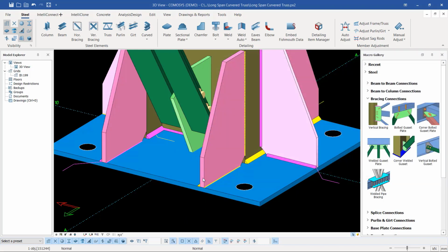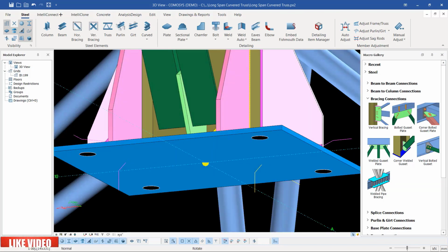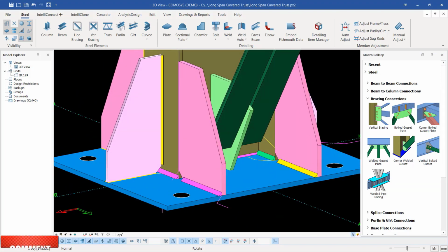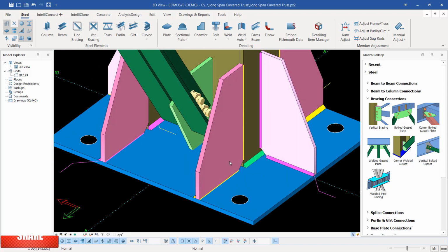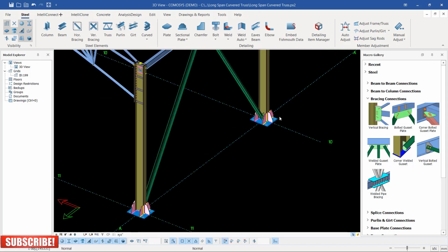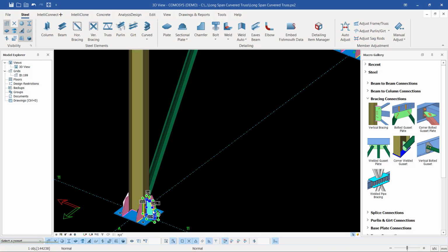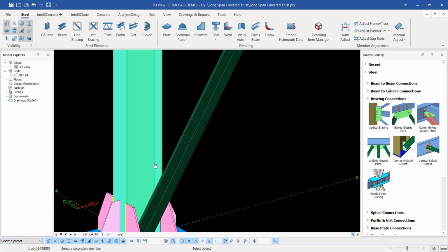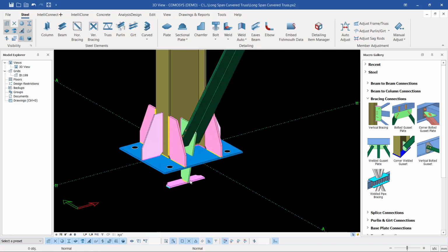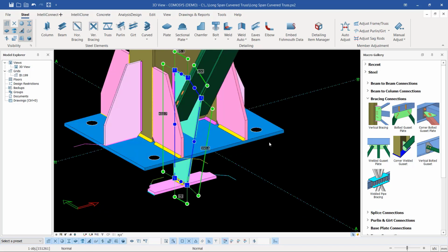And you can see that has changed, but it hasn't responded well. But that's it, and we have created that in place. So I'll go back and apply the same thing at this far end, and come back there and click the column and apply that there. So I'll go ahead and modify that: select, then press letter M and enter on your keyboard.